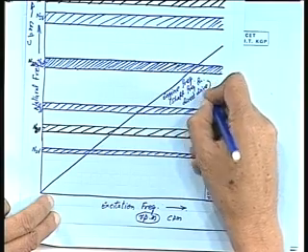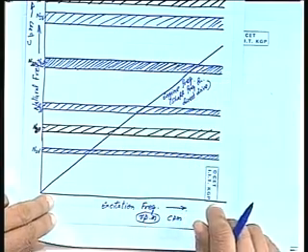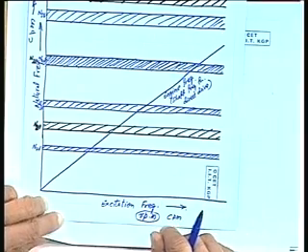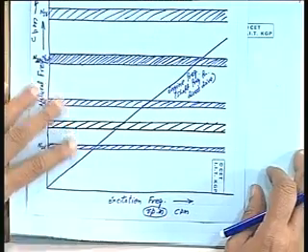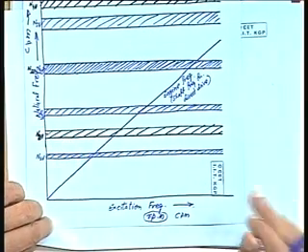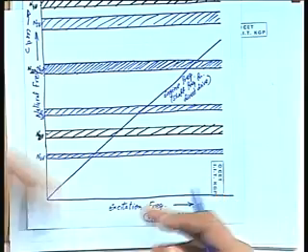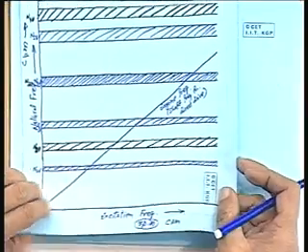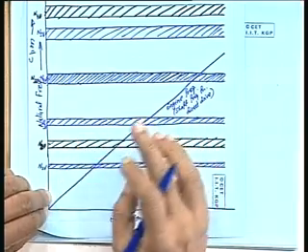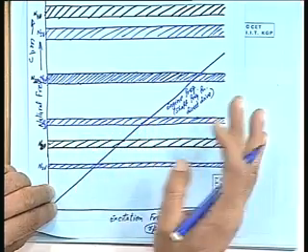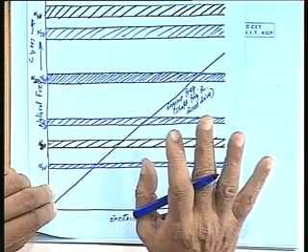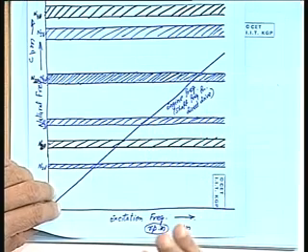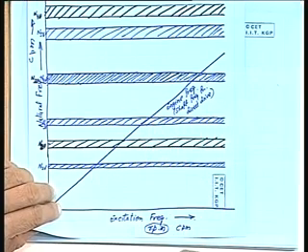If it is 1:1 gear ratio, direct drive, then this will also be the shaft frequency. If suppose you have a gearing ratio between the shaft and the engine output, and the gearing ratio is say n, then the shaft RPM will be n times the engine RPM. Usually you try to step down.